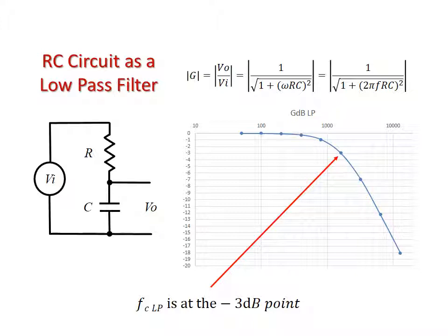So the cutoff frequency for the low pass filter is at the 3 decibel point. Remember, decibels is a logarithmic scale, though this isn't a logarithmic graph. So every single value as you go lower in decibels is increased cutoff. Essentially, the signal is getting increasingly quiet as we go up through frequencies. It's not linear. Anything to the left of that, you can see it's less than 3 decibels, which isn't that much of a cutoff.